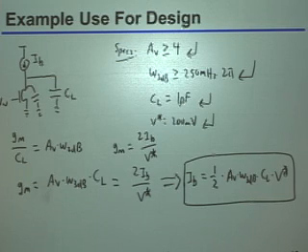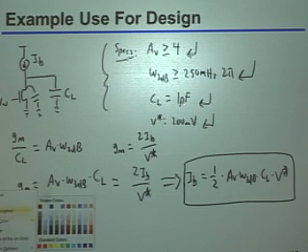Okay. So you said that my output resistance is not infinite. So in particular, which circuit-level parameter is it that may not necessarily be met because of that? Channel length modulation. I mean, there are 3 specs here that I said I wanted to meet. Which one of those 3 might I potentially not meet? Yeah, the gain, right?